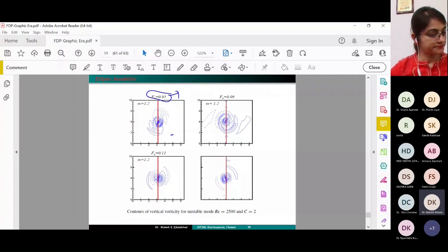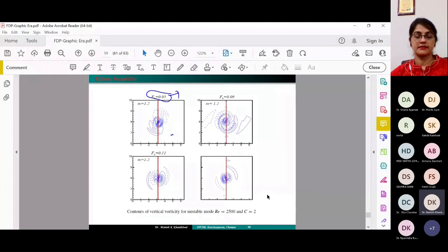And in fluid mechanics, it comes in terms of the Landau equation. It is nothing new, but a famous equation. As a solution, I have given dx/dt = ax - bx^3 or + bx^3. Then the supercritical and subcritical bifurcations. Those bifurcations we can analyze near the linear stability analysis. And linear stability analysis is completely eigenvalue problems. So we have to convert to the eigenvalue problem and calculate the different modes in the stability analysis. And the most unstable modes we have to pick up and then check whether the flow is stable or unstable.